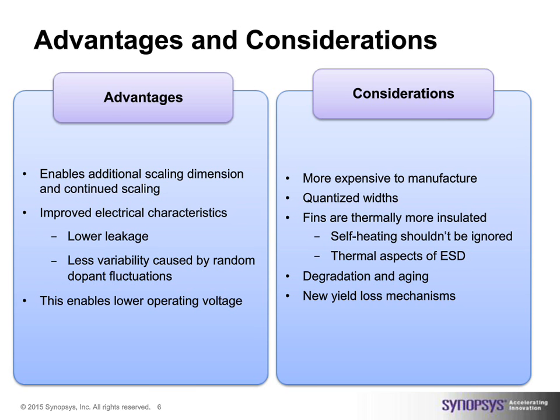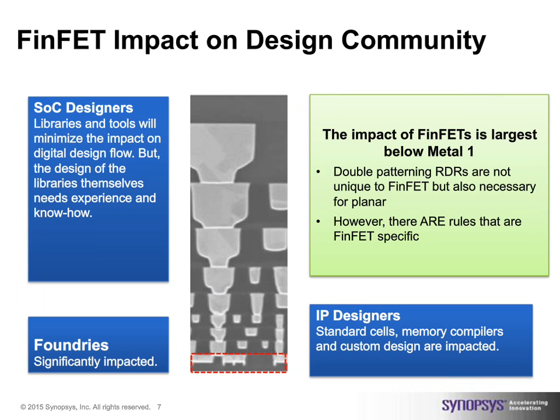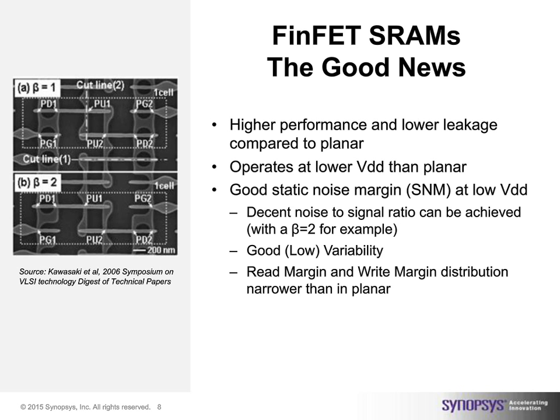Now, this will have implications on the users, but it depends on which users. With FinFET becoming popular, the implications will be mostly on the foundries who are making this happen, building this metal one layer, building the transistors, building the fins in a healthy way. Also, it will impact the IP designers while they're designing the standard cells or their memories. They need to take care of these newer structures and build them properly. But there will be lesser impact on SoC designers. SoC designers will use the libraries and the memories, but their flows and their tools will be almost similar to what we have seen before. So the implications are far more on the foundries, a little bit less on the IP designers, and far less on the SoC designers.